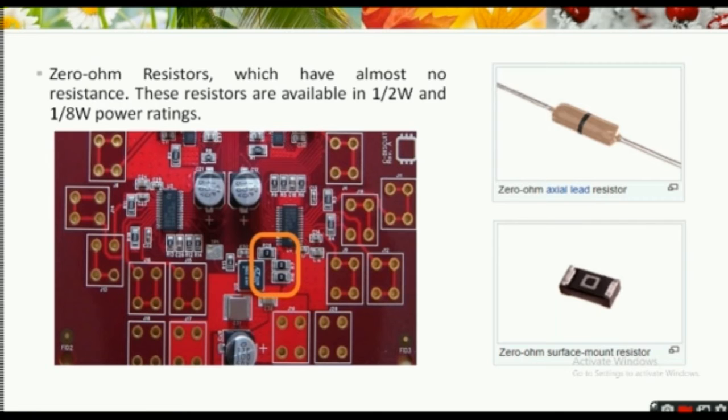As you know, today the components in printed circuit boards are inserted by automatic insertion machines to speed up the manufacturing process rather than manually by humans. For jumper wires, a separate machine may be needed or the wire should be manually inserted by humans. So we use 0 ohm resistors. These resistors can be easily removed and can be easily replaced with other resistors if needed.